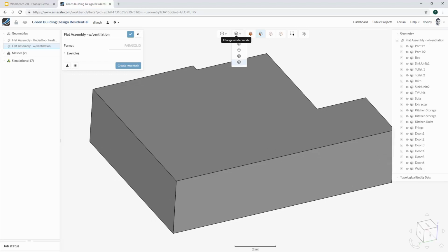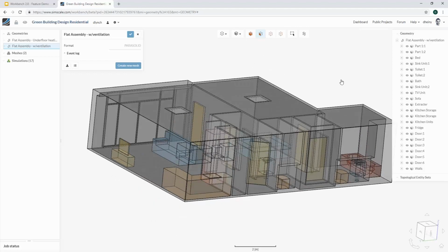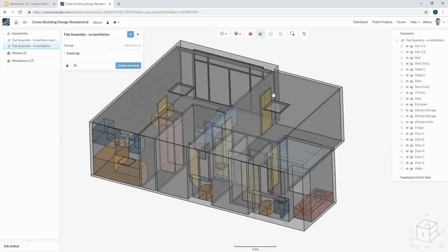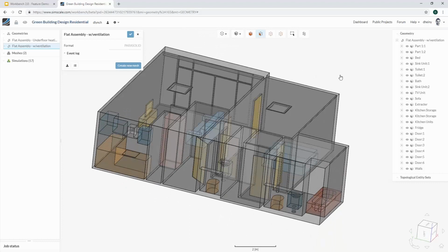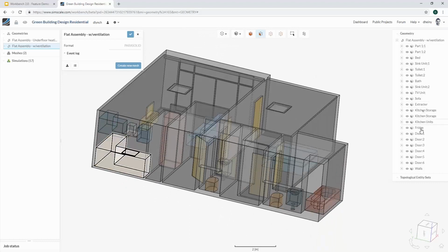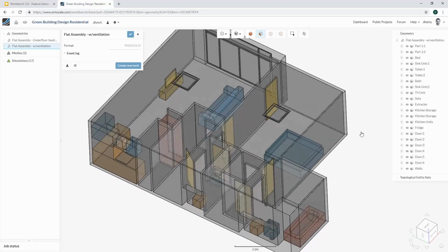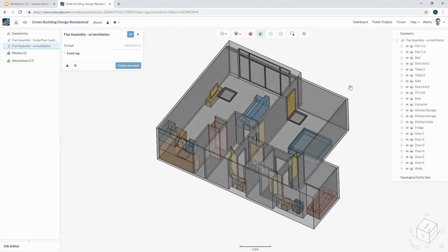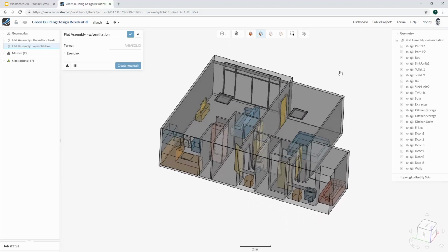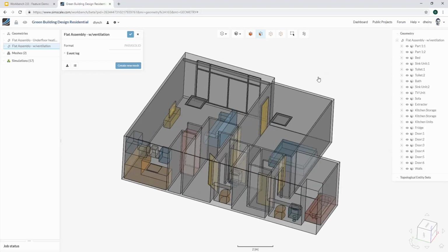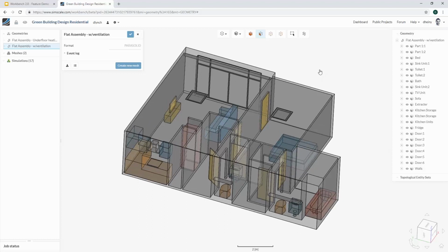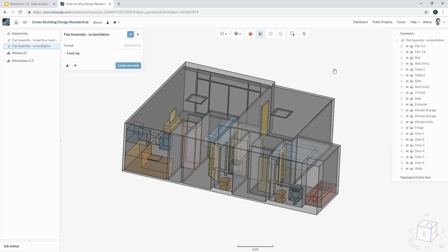Regularly, what we've seen is that something like this comes in handy. With one view, I have the entire context of my CAD model. I see what I've defined. Again, on the right, you can see names are persisted, colors are persisted, and with the translucent view, I get an immediate overview of where is what. I can also use this translucent view during my assignment operations, as we're going to see later. When I'm defining boundary conditions or assigning result control items and the like, I can use the translucent view to increase my confidence that I'm assigning things at the right position.